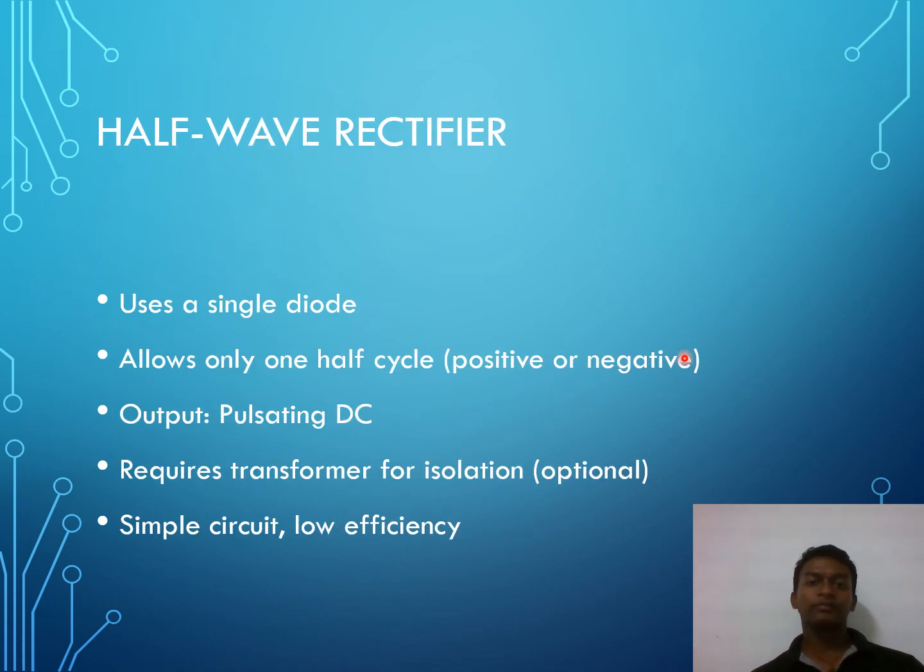Half wave rectifier. In a half-wave rectifier, only one diode is connected to the AC source. It conducts only during the positive half cycle of the AC input, and it blocks the negative half. As a result, the output is pulsating DC but contains large ripples. This makes it inefficient for most applications. However, it is simple and often used in basic signal demodulation.